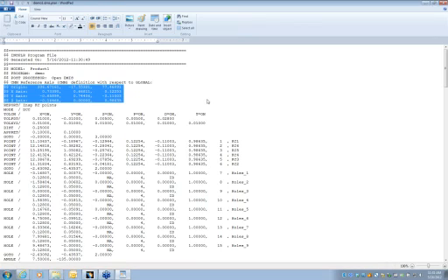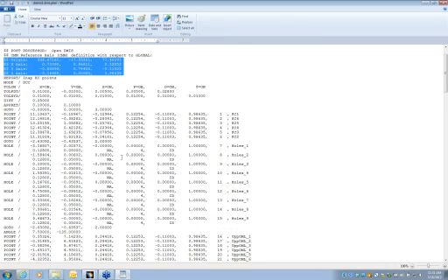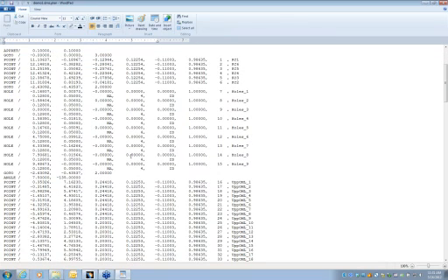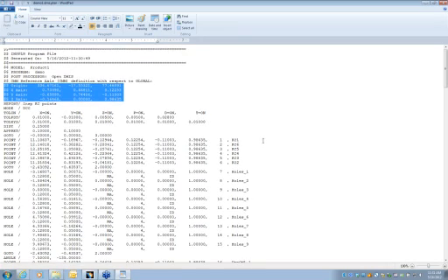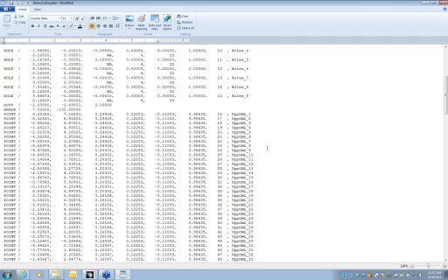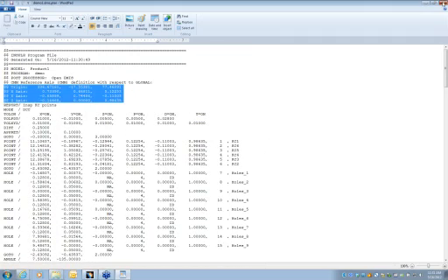We could have programmed this whole part in aircraft axis or absolute axis and still pick that second axis to align the probe. I just chose to pick a local axis. We have some tolerance information, some of the input that the machine is going to be using for moving around, all of our names, and then we have the different points, different hole information. So Douglas used to call this Cupus, Northrop calls it Quade, but it's basically the key characteristic points. It's what is in our plan.